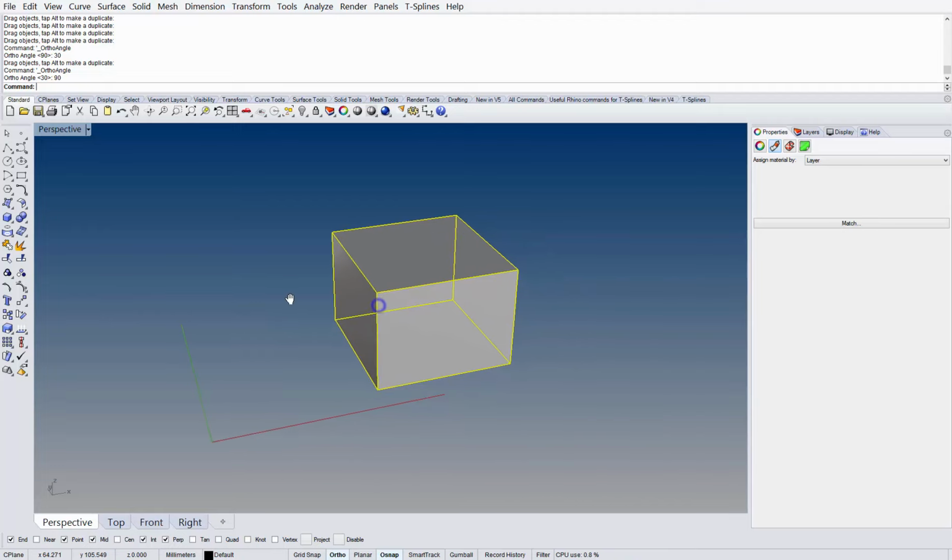So the other thing that's important in Rhino is preciseness, and preciseness comes with snapping objects together. And this may be turned off if you're on a Mac, but if it is, you're going to look for the button that says OSnap, and you're going to click it, and this set of options are going to appear. And so these are the snapping options that let you snap an object from point to point, for instance.